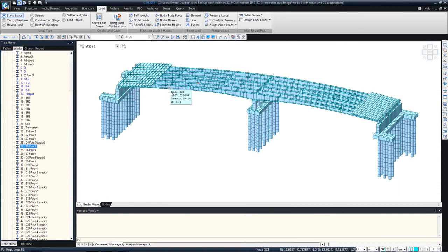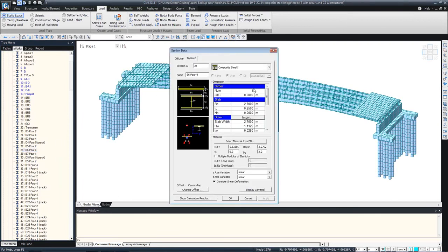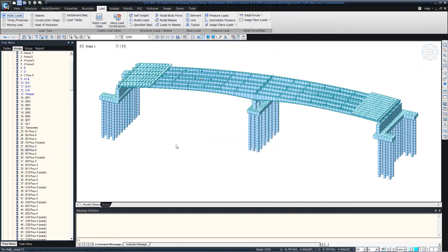The other important thing in curved bridges is that you should also create intervals whenever there is splicing to get the splice forces. So that's why you can see the nomenclature that I've used here is based on the splicing information. So if this is girder B, then I have splices at 7 locations, and I've named them separately. And each pouring sequence has been named with different composite sections. So they can be the same section, but just name them differently.